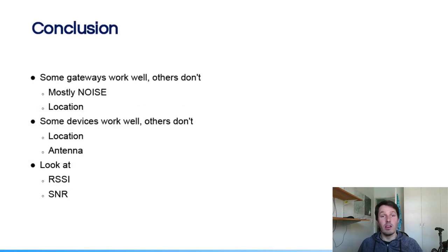Some gateways work well, others don't. This is mostly due to their installation location and the amount of noise the gateways hear. Some devices work well, others don't. This is mostly affected by installation location and the antenna. RSSI and SNR values are our friends.